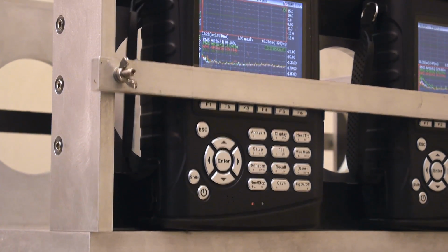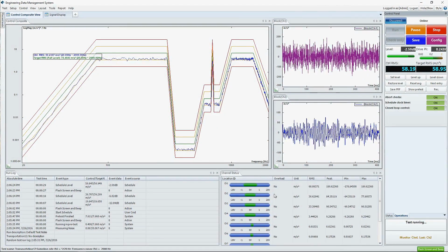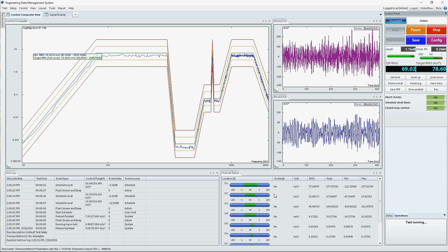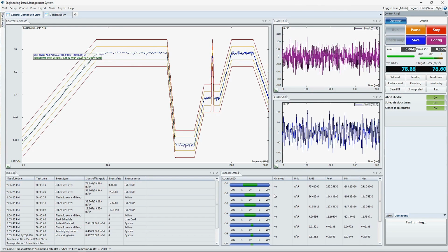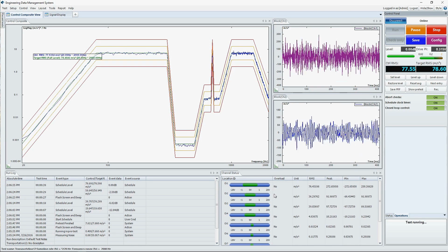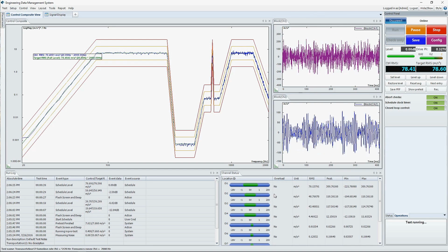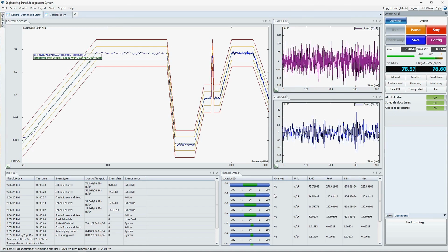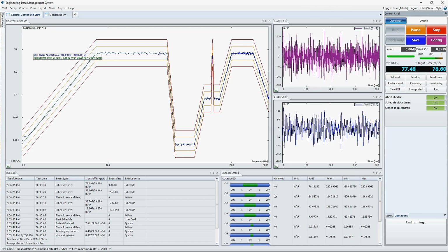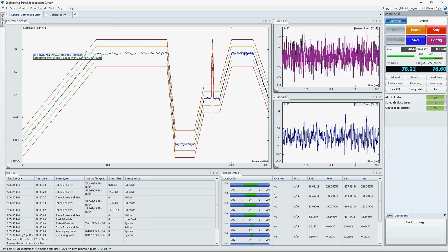Input channel dynamic range is a key parameter for achieving superior random control. The dynamic range may be thought of as the ability of the controller to control both a very large signal and a small signal within close proximity of each other. In other words, a steep drop or rise in the profile will be difficult for a controller to manage if the dynamic range is poor, less than 90 dB. The Spider controller series can achieve an input dynamic range of over 150 dB using dual 24-bit A to D converters on every input channel.